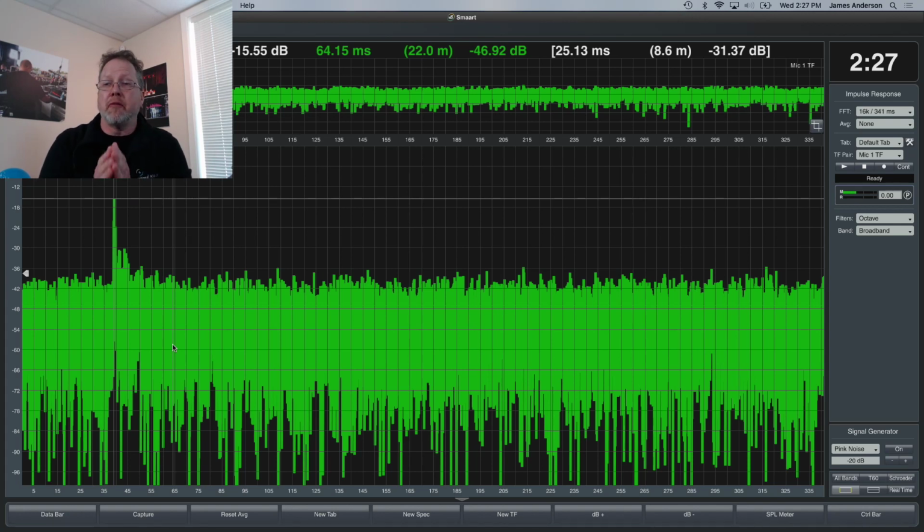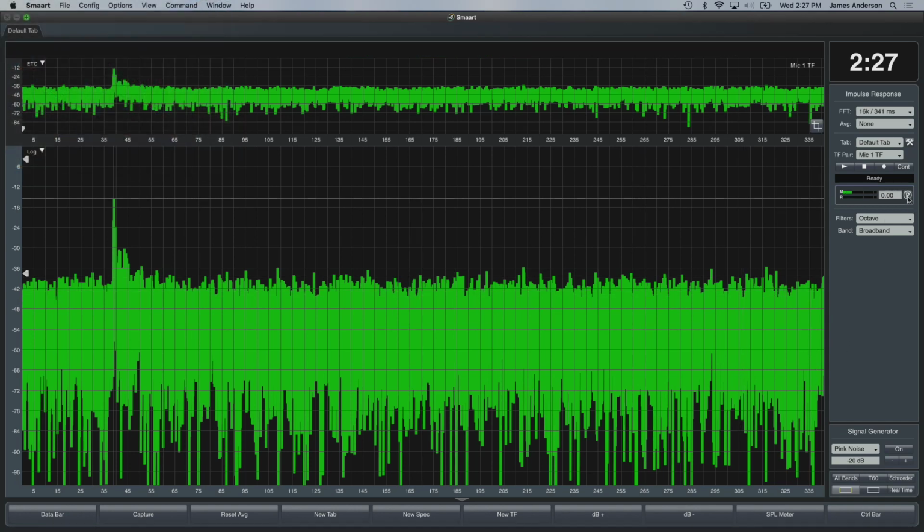All right, so remember, the first thing I always say is set your delay. Let's get the best mathematical correlation. So let's see if that has an impact. What I'm going to do over here is in the measurement engine, there's a button that's a P in a circle. That always makes me grin. I click on that, and it's going to set the peak time to that delay time of 39.02. So that's the only change I made, but now I've timed my reference signal to my measurement signal.